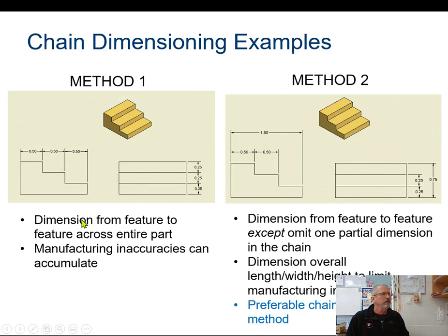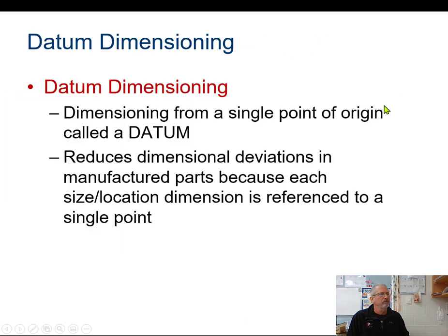This is really a type of dimensioning that we will almost never use. We'll always use chain dimensioning: we will go one right after the other and then do the overall. This is used quite a bit in civil engineering and architecture. This is an absolute no-no right here. These two should go over here where the shape is. And you'll hear me talk about Anthony all the time because Anthony is the one that drew this. We'll talk about that in a minute.